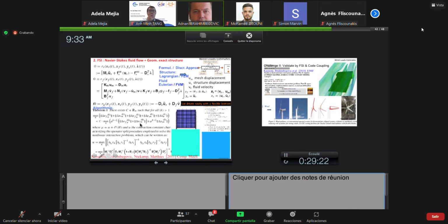And in order to make sure, again, this is done with sequential resolution by splitting the codes. First you hit solid, then you hit fluid. Solid is done by FEAP, fluid is done by OpenFOAM computation. And if you want to be stable, there's a certain type of procedure you have to do. In other words, you have to move solid first and then fluid.